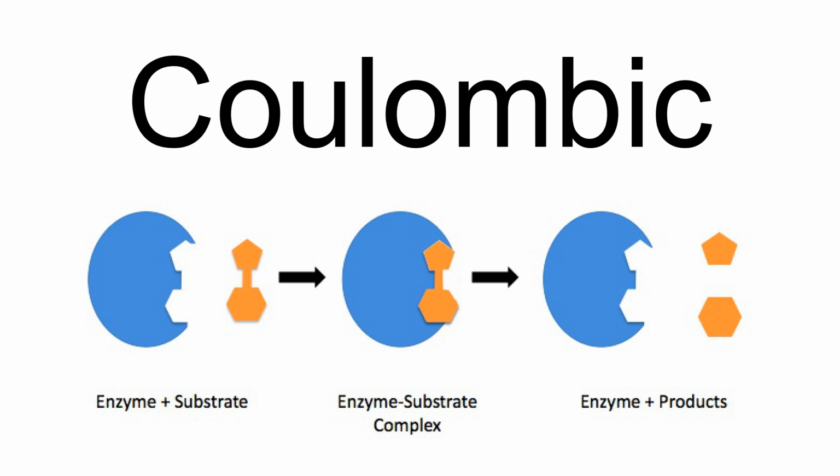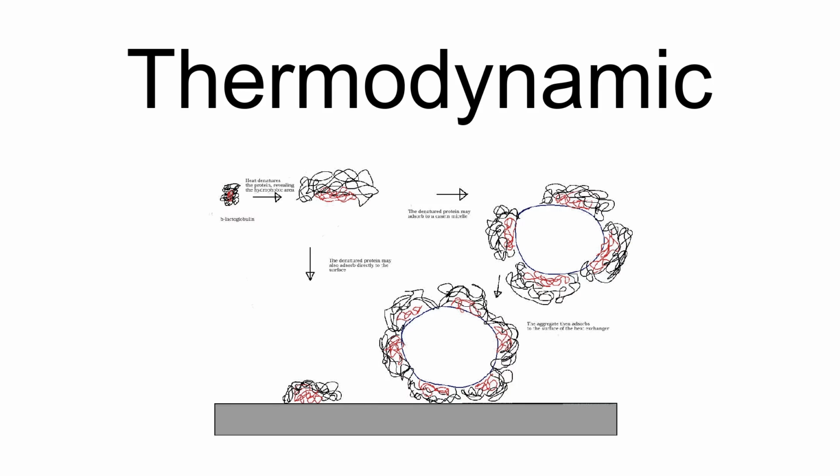Protein adsorption can also occur as a direct result of heating a mixture. Protein adsorption in milk processing is often used as a model for this type of adsorption in other situations. Milk is composed mainly of water, with less than 20% of suspended solids or dissolved proteins. Proteins make up only 3.6% of milk in total, and only 26% of the components that are not water. These proteins are all responsible for fouling that occurs during pasteurization.